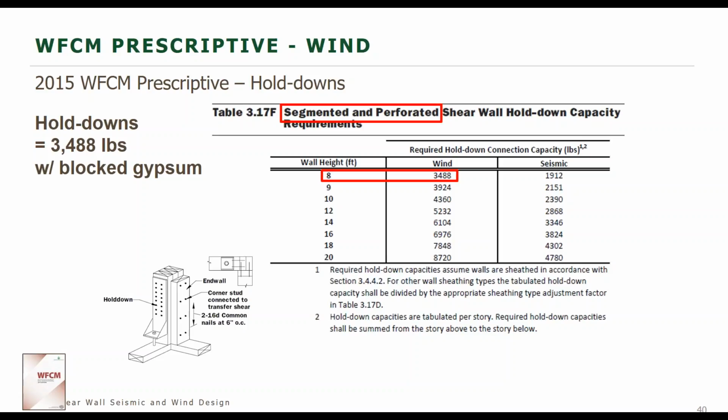And what was the second part of that question? No, that's okay. What do we assume in the wood frame construction manual as far as dead load offsetting one or the other of those? I think Michelle briefly alluded to that. For the hold downs in the prescriptive approach, both wind or seismic, we don't have any dead load offset. There are provisions in the engineered approach for the hold downs to have a portion of the dead load used to offset some of that uplift.